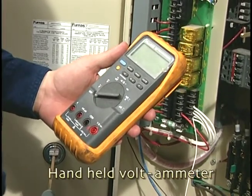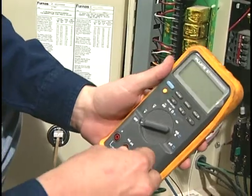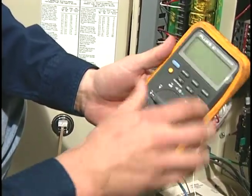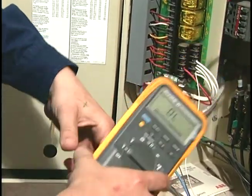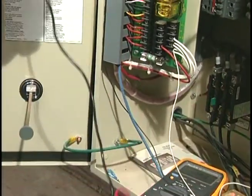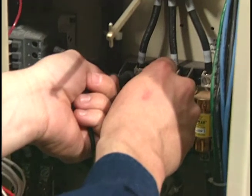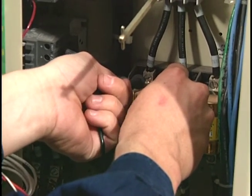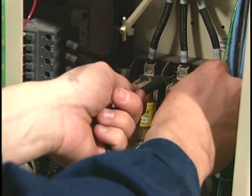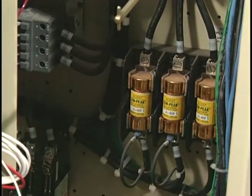To take voltage readings, the technician attaches the lead wires to the meter. When reading voltage on a three-phase motor, the potential between each phase is measured. For consistency, the technician reads the phase-to-phase voltage from left to right. In other words, phase 1 to phase 2, usually designated as L1 to L2. Phase 1 to phase 3, L1 to L3. And phase 2 to phase 3, L2 to L3.